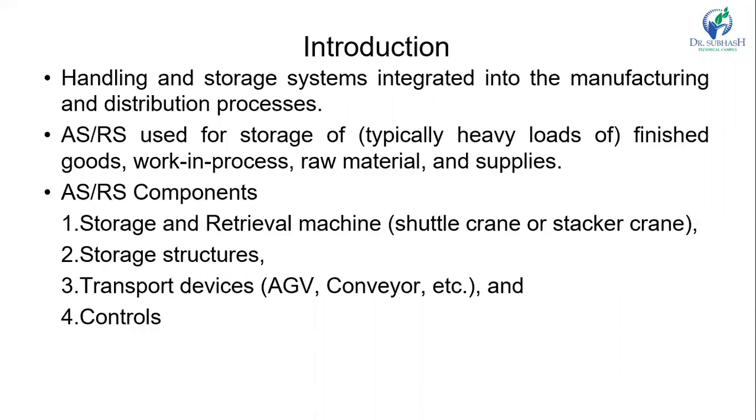The importance of it for management to make manufacturing decisions based on accurate real-time information can be understood from the fact that in-process material rarely spends more than 5% of its time being worked on, and the remaining 95% is spent in transit or storage. Thus it becomes easier to visualize the role of material handling and storage system within an automated factory.